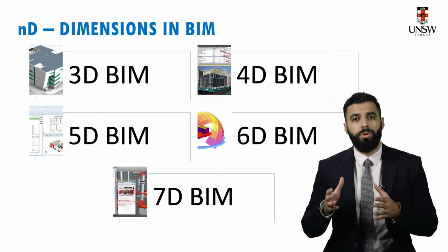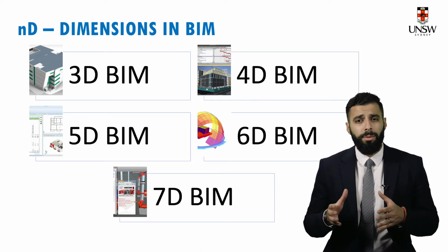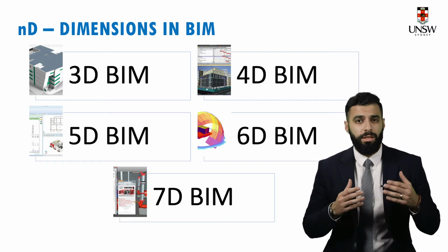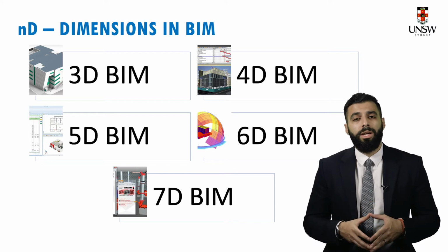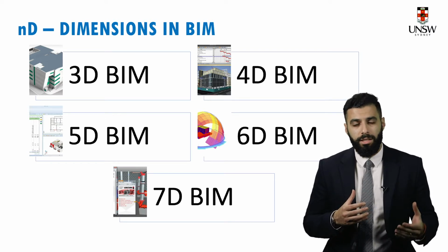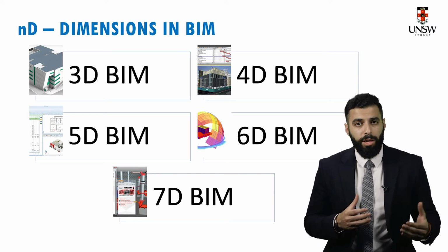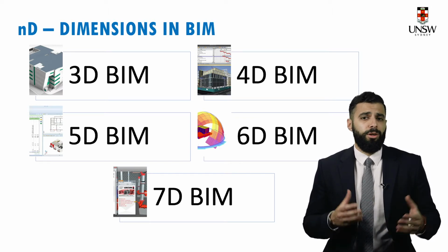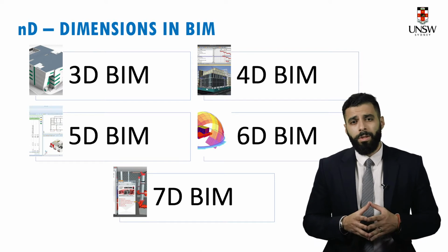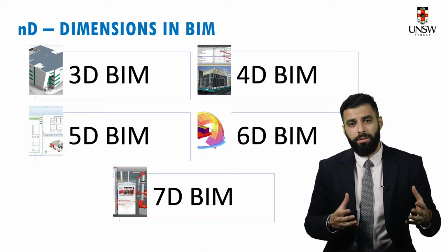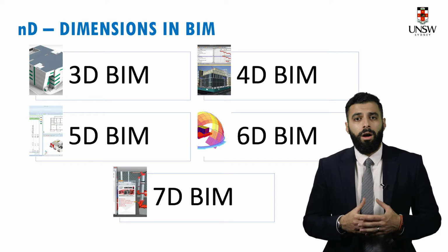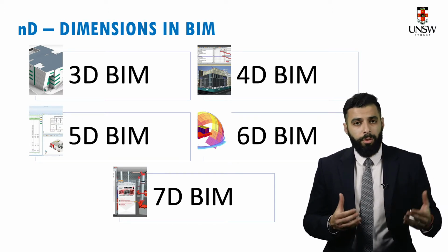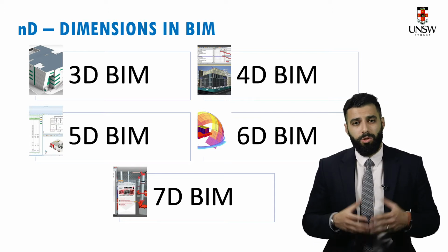Let's move on to 4D BIM. Now, 4D BIM is where things get interesting, because it is in this dimension where you start incorporating additional data sets, namely a timeline to your digital model. This is often in the form of a construction schedule. So once you do that, you can simulate the progression of the construction activities. So you can monitor the process of the construction as it happens on site.